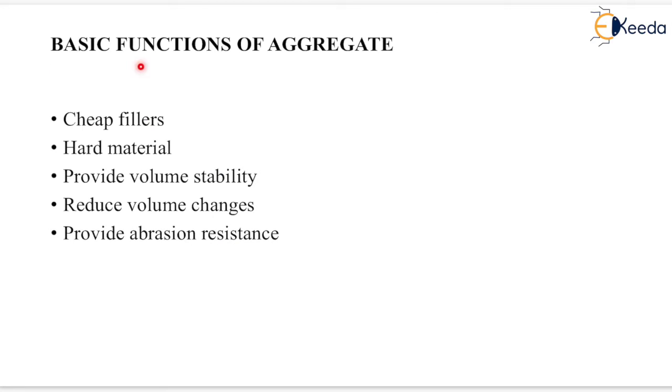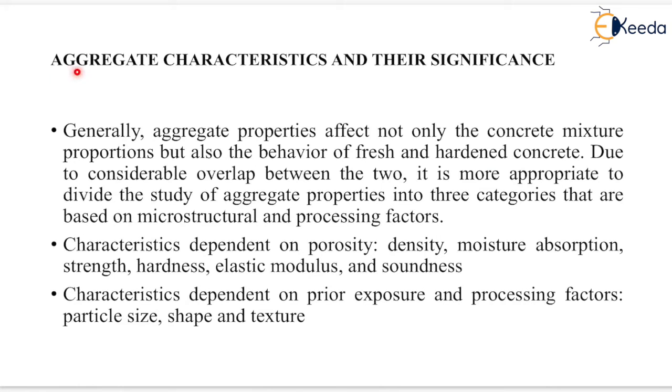Now basic functions of aggregates. Cheap fillers, hard material, provide volume stability, reduce volume changes and provide abrasion resistance. Now characteristics of aggregate and their significance.